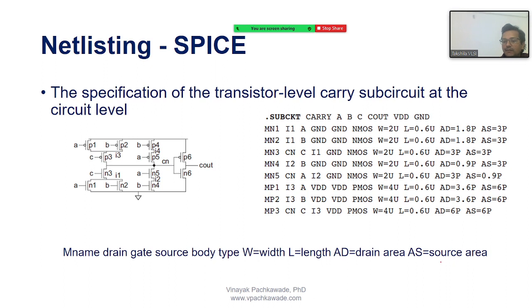So parasitics, remember one word, parasitics or stray, are very important for the layout engineers. They need to understand in the given circuit when the physical layout will be generated, where are the parasitics and how to minimize them. So basically engineers in the layout team try to put all cells very close to each other so that the parasitics can be minimized, because if R and C can be minimized, then what happens?